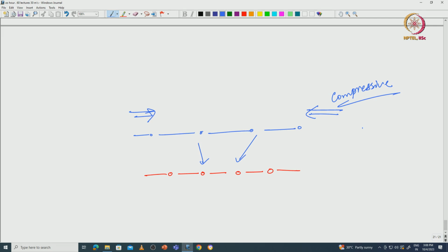So typically in compound semiconductors like the III-V gallium arsenide, indium phosphide family, people try to exactly match the lattice constant, A equal to A naught, so that there is no strain generated, so there is no dislocation that will come. So the material quality is very good if there is no dislocation. The device performance is not adversely affected, and you can grow very thick layers also without cracking.